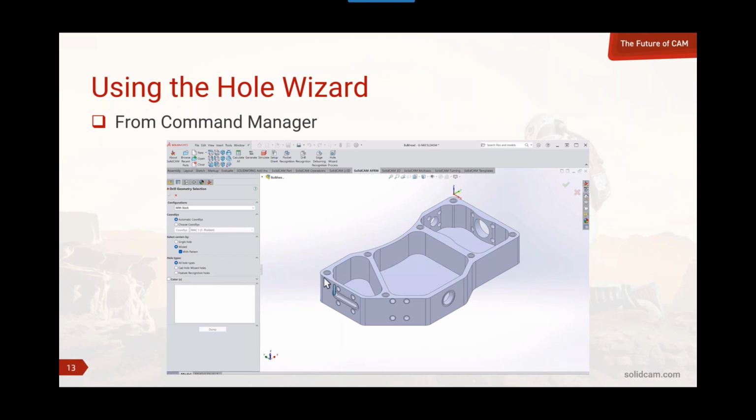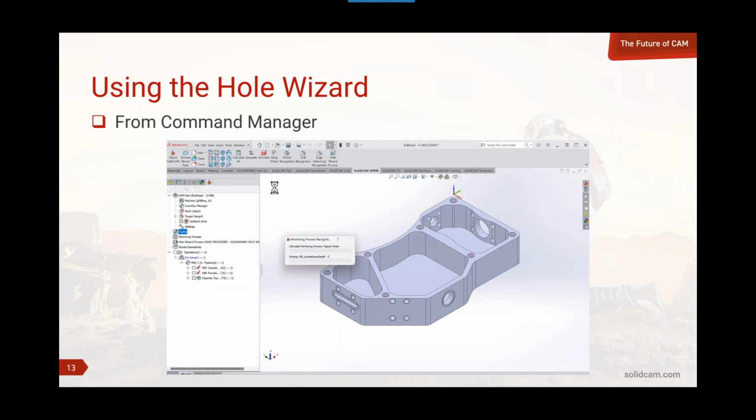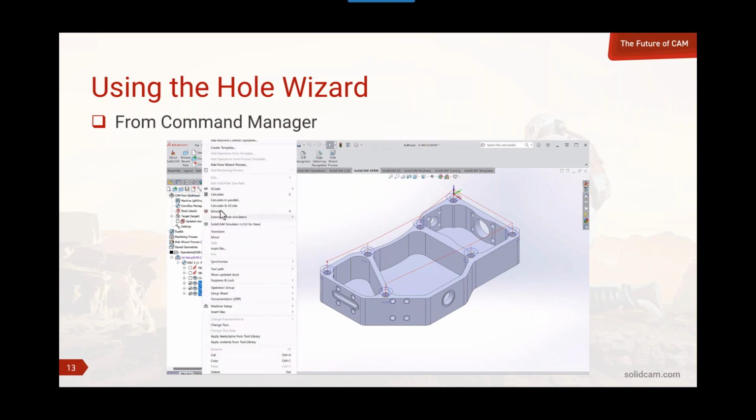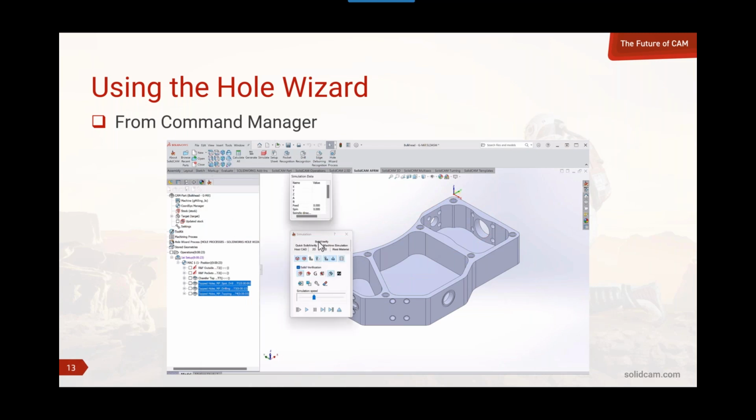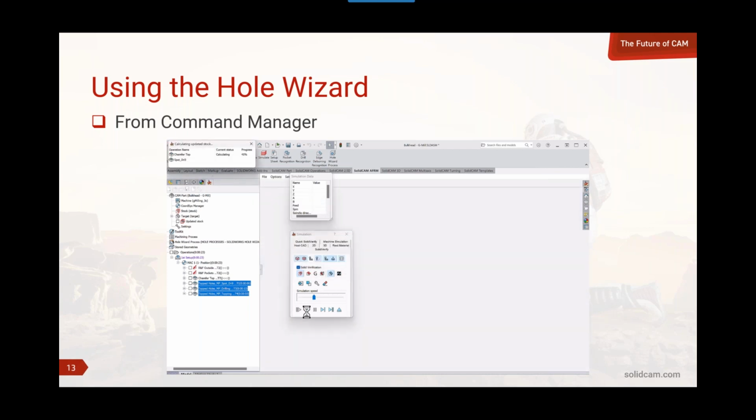Here's the list of where the hole is. So if we pick a hole, the system is going to find that hole, and it's going to find all of the instances of that hole within that CAD feature, okay? Or based on feature recognition, the similarity of that. And then it's going to calculate and run this through all the processes that we defined in the hole wizard table, and it's going to generate the 3 different operations: spot drill, drilling, and tapping. Notice also, everyone, that it also recognizes the exact type of hole. Absolutely, we are doing feature recognition that captures that data and that information.